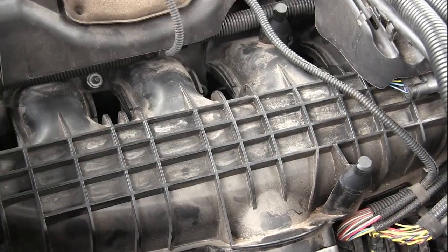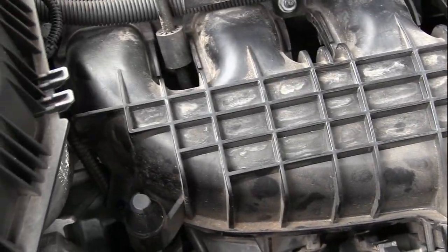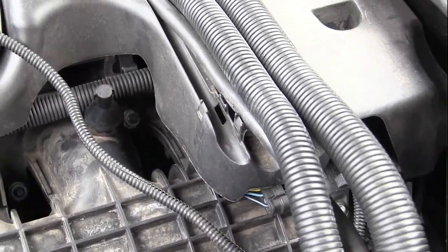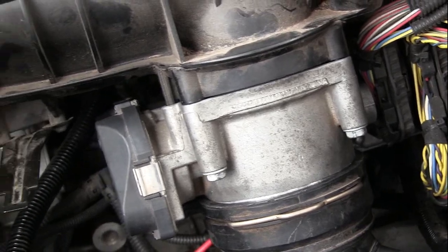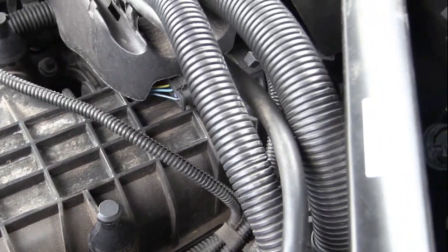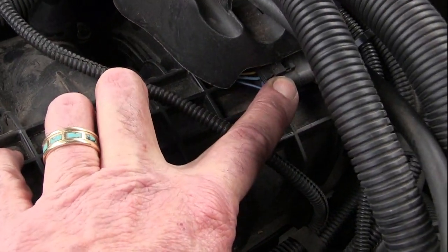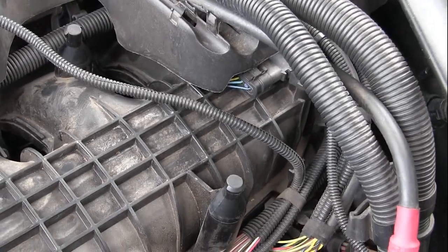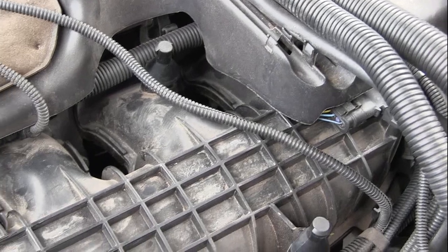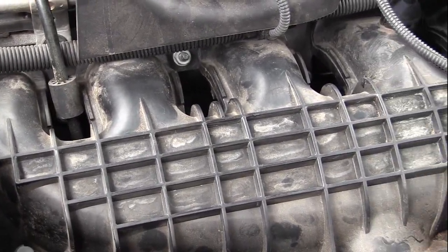I've removed the air filter assembly and housing off of this engine. Now we need to look at the manifold, and we need to look for an access to get the chemical into the engine. Right away, I don't see any type of vacuum on this engine, but I do see that I've got a boost sensor, map sensor right here in the back of the intake. Now if I pulled that out and I put the chemical in there, all of the chemical would go to the rear two cylinders, and these front cylinders wouldn't have any chemical application.